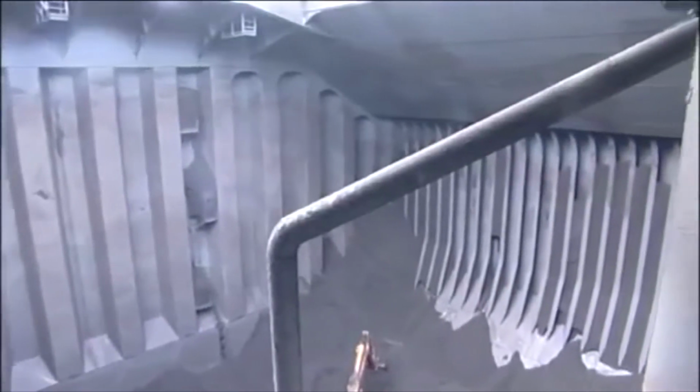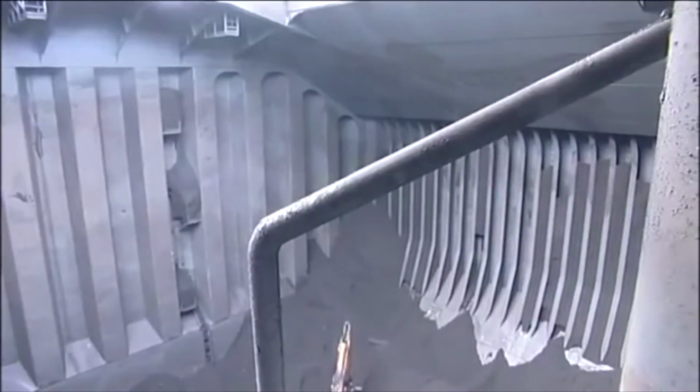Despite all this steelwork, the ship is not a rigid structure. In fact, for it to function effectively, there must be a degree of flexibility. However, overloading any one of the holds will cause excessive stress to the structure of the vessel. And if a cargo is poured into one end of a hold and piles up, the pressure acting on the transverse bulkhead will increase.